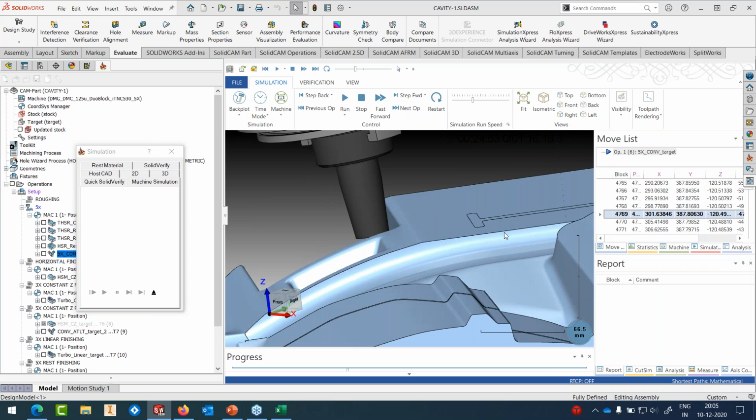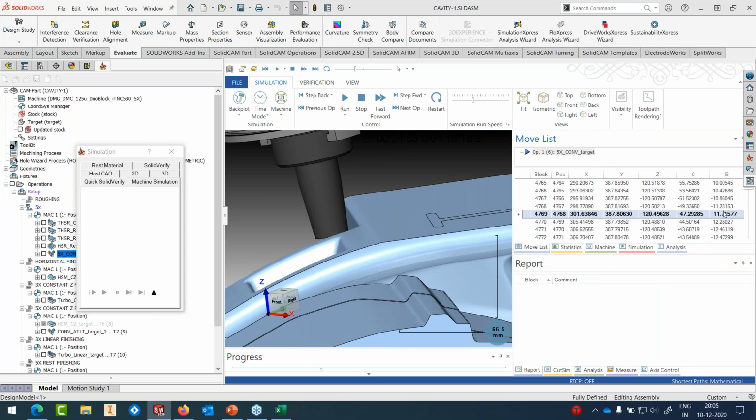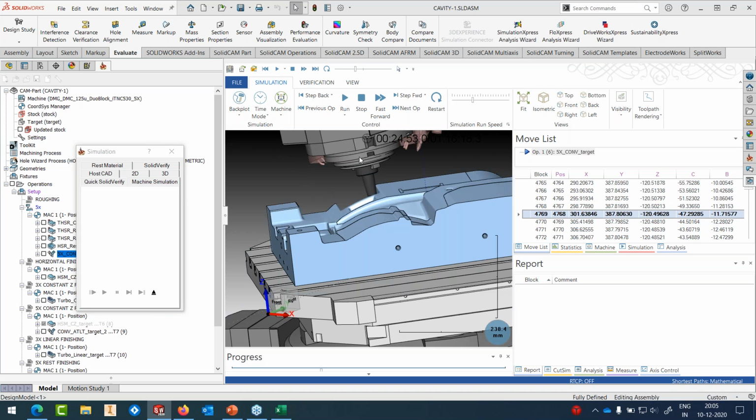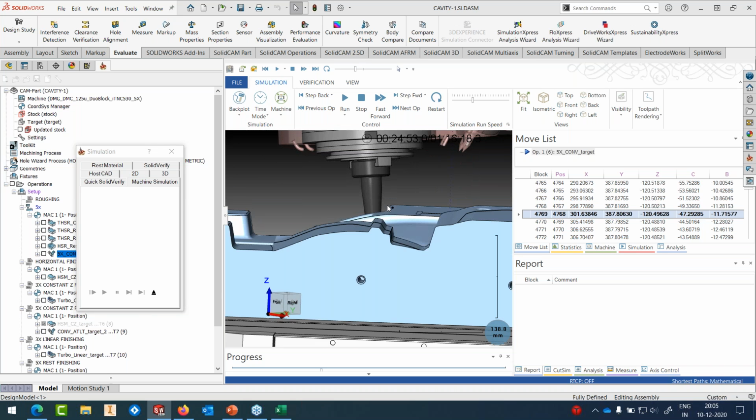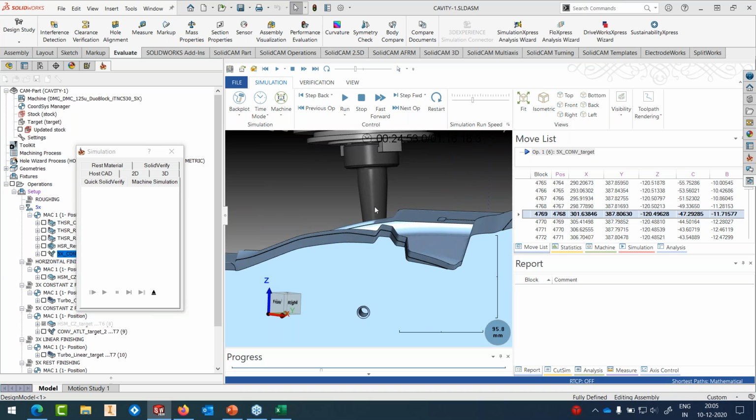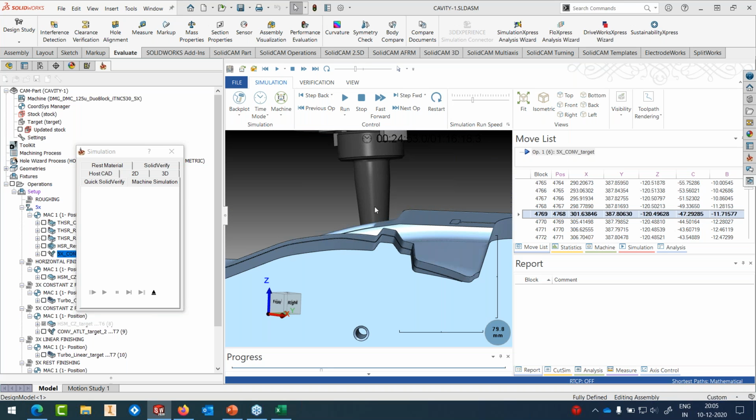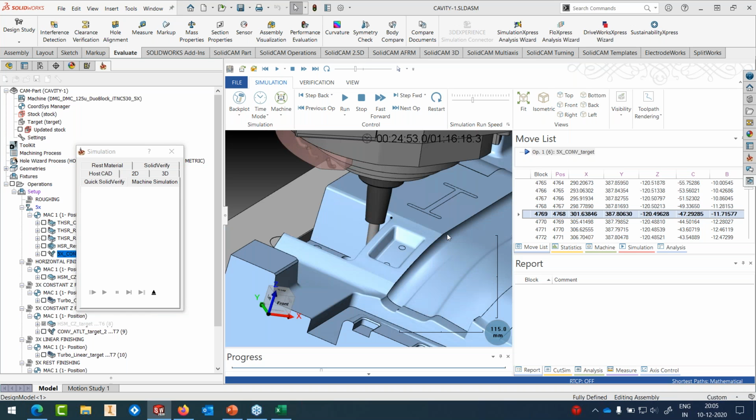You can see the B and C values here. The BC values mean that the toolpath is now a full 5-axis toolpath. It has already tilted, and it's avoiding the collisions against the holder, taking into account the part geometry and the stock, obviously. From a simple 3-axis roughing, I have now created a 5-axis roughing.